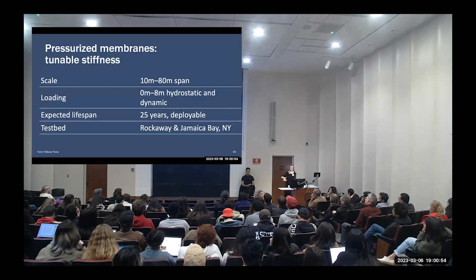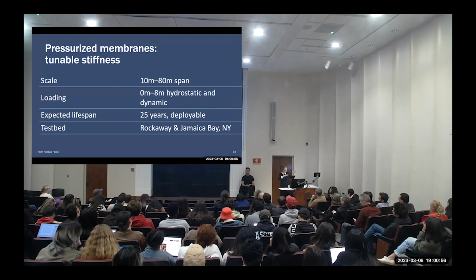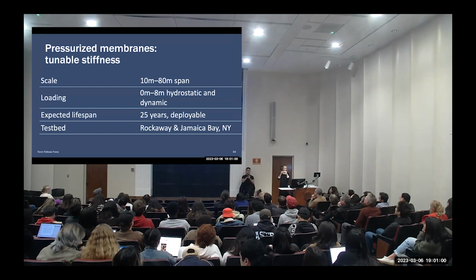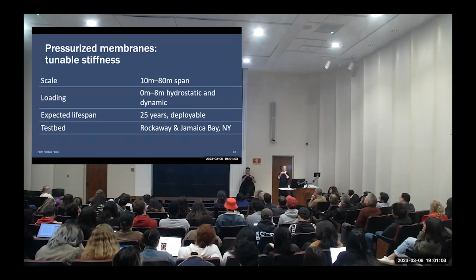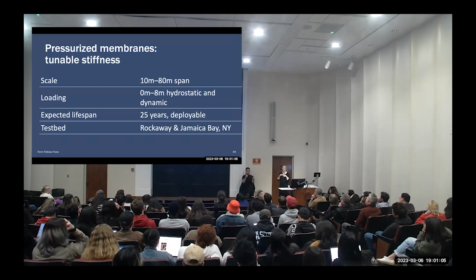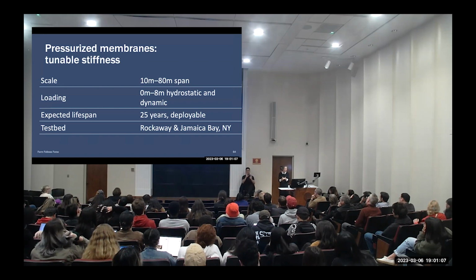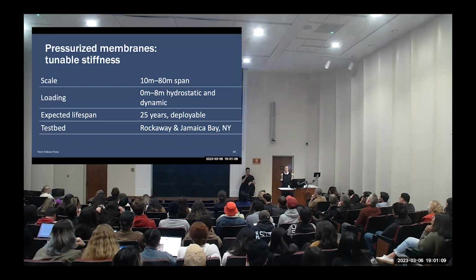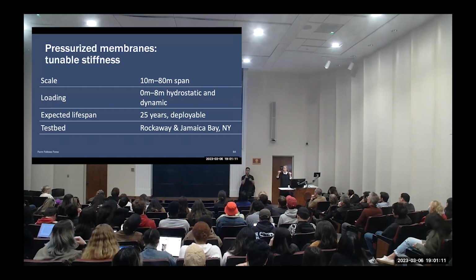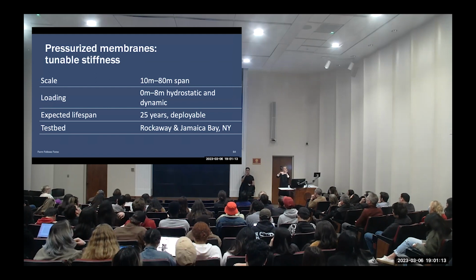Okay, I'm coming now to kind of close the circle. I'm going to talk about pressurized membranes. So these are very flexible membranes. They don't have any stiffness. If you don't do anything with them, they will just flop down. And they can only be loaded in tension, right? If you put compression in them, they will just wrinkle.